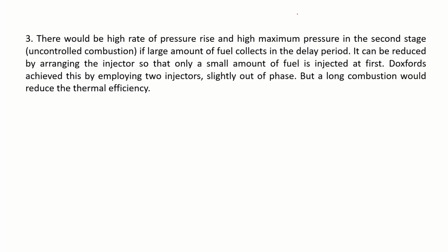In a diesel engine, if I increase the compression ratio, it is always better. Already we are using a compression ratio of 20 to 24. If you further increase the compression ratio, to withstand high pressure we have to make the piston much stronger and the cylinder stronger, leading to heavy reciprocating parts that lead to inertia, which leads to low engine speeds. That's another kind of problem. So we have to find a middle path for this.